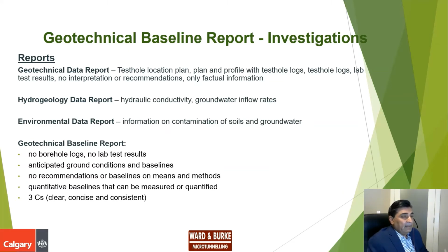Okay. Then in a geotechnical baseline report, we don't provide any recommendation. We only provide baselines on means and methods. Sorry, we don't provide recommendations, and we don't provide any baselines for means and methods. That is contractor's responsibility. We provide baselines for ground conditions, and contractor has to select equipment based on those baselines.